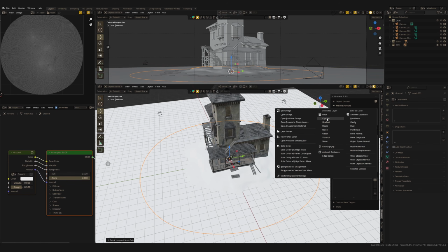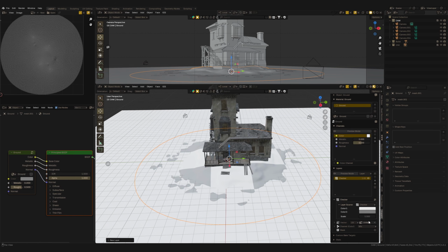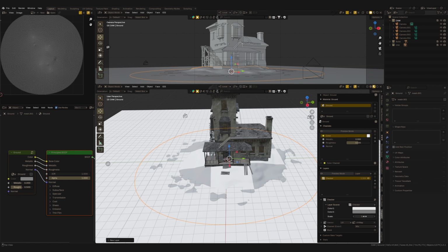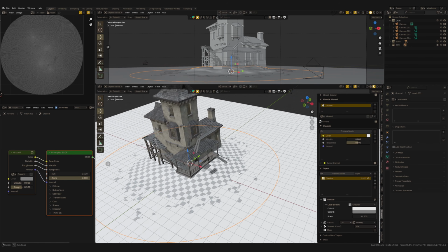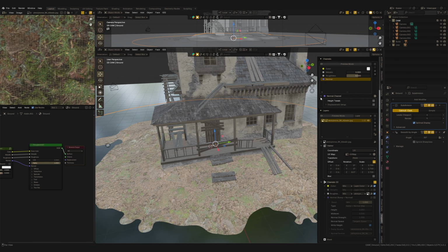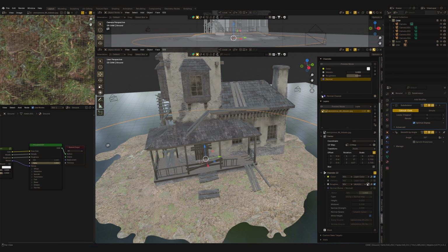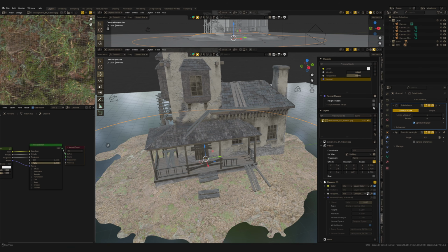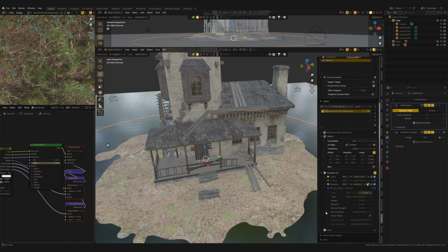By the way, we can also add a layer with a checker texture to check if everything displays well and there are no weird UV stretches. And that's the favorite feature I mentioned. It's our ability to work with displacement. In the normal channel, we can turn on displacement setup to enable working with displacement in Ucupaint.